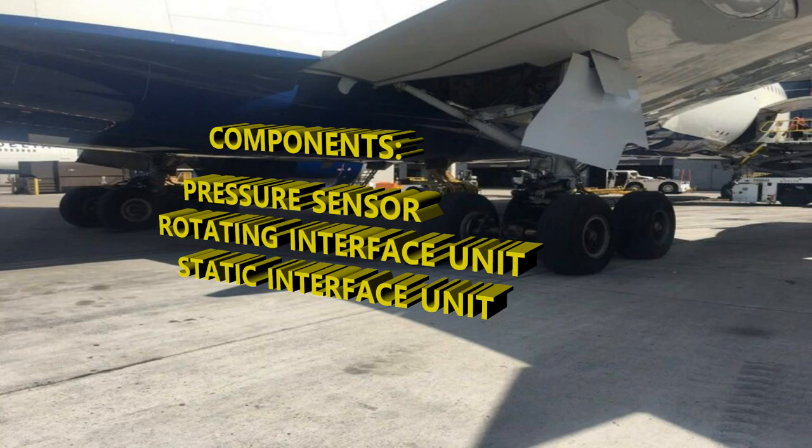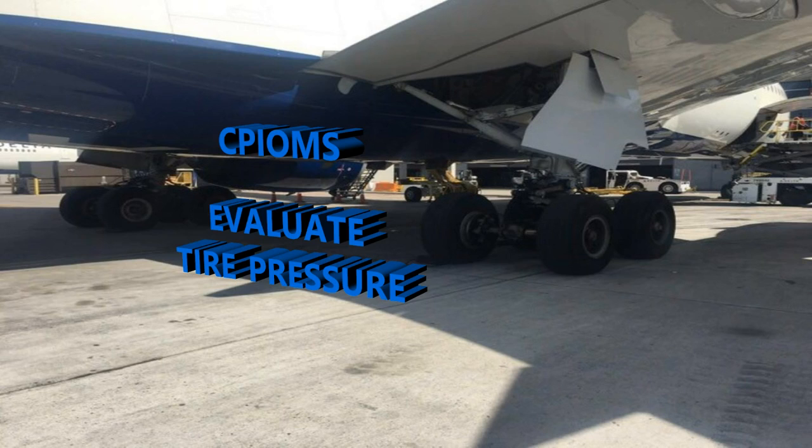All right, and all the data is going into the CPIOMs. Those are your core processing input-output modules that are going to identify and determine whether or not the tire pressure is where it needs to be. If it's too low, then the warnings are going to be sent to displays about that. Whether it's either one or more of the wheels are too low, or there's a difference in the pressure between the two.